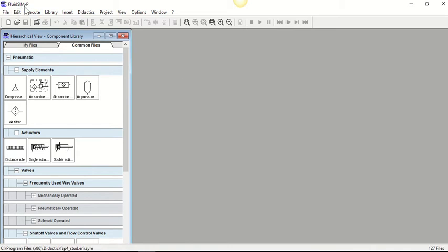Okay, so P for pneumatics. Very important that if you're doing a pneumatic circuit, you use the pneumatics Fluid Sim rather than the hydraulics, because it won't simulate properly for you. So just make sure that's always the first starting point, to make sure you're in the P.